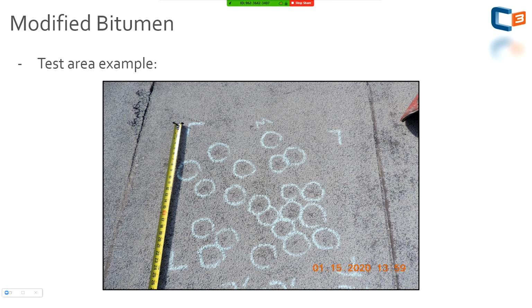So this is going back to what kind of constitutes damage. And in this case, we had fracturing of the asphalt surrounding the reinforcement, but the reinforcement itself was intact. The roof was not leaking yet, but this is still reduction. This is still damage.